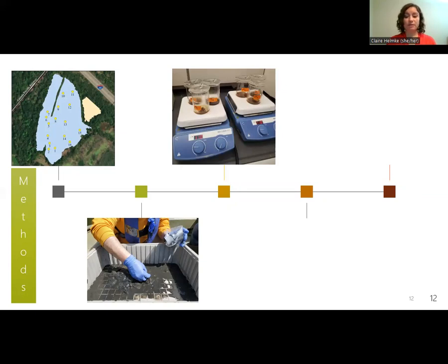Using a flame atomic absorption spectrometer and following EPA method 7000B, we were able to identify the extractable concentrations of cadmium, copper, lead, nickel, and zinc from the formerly solid sediment samples. To accurately assess the spread of the metal concentrations within the sediment, we need information on the X, Y, and Z plane.